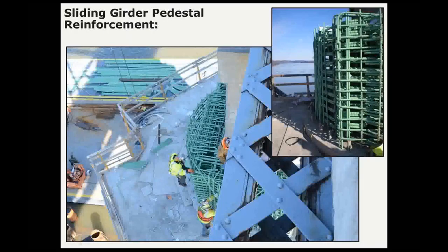It's packed about as tight as you could pack it in there. And that's because that tuning fork girder is going to sit on either side of this pedestal, and then all of the wind loads, the lateral loads that the truss experiences, are going to get drawn over to this permanent pier because it's so much stiffer than that temporary tower.